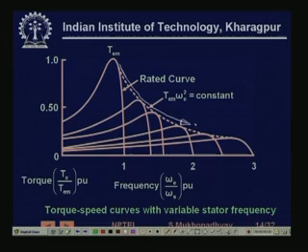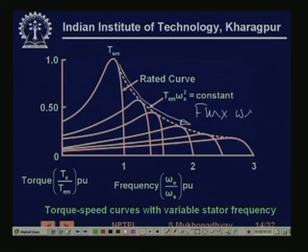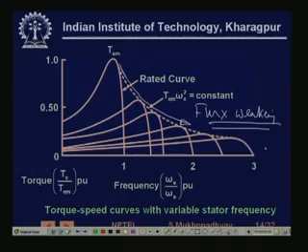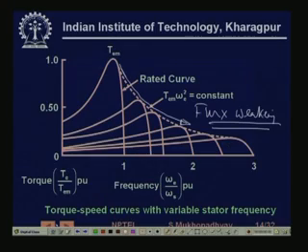If you raise it higher, keeping the voltage constant, the flux level is going to fall. So this is a flux weakening kind of region. Perhaps you can recall the similarities which you found in the DC motor characteristic. There also we had a flux weakening zone. In that zone the torque will fall, basically because there is a maximum torque achievable with a certain stator current. These are all envelopes of operation, and the torque will fall because the air gap flux level has come down, right.